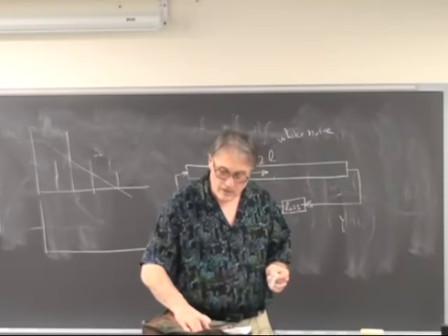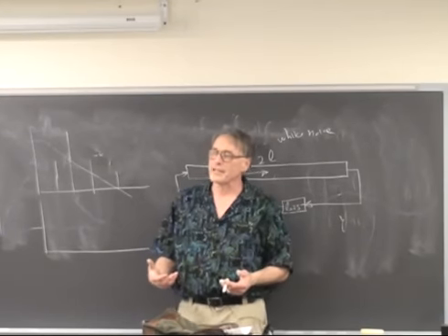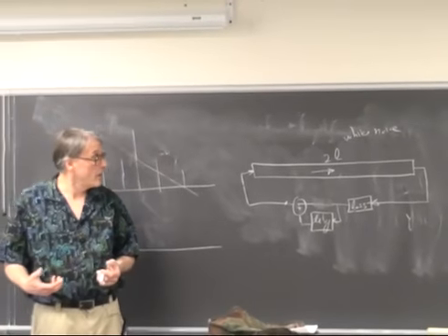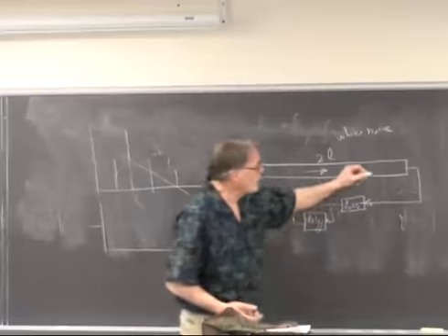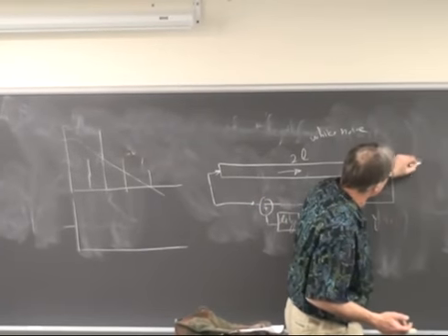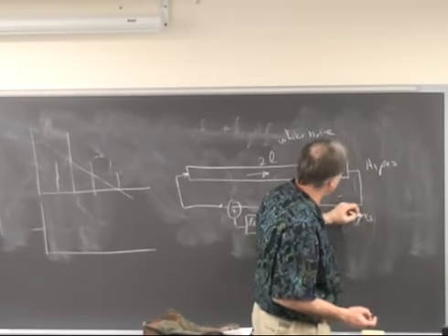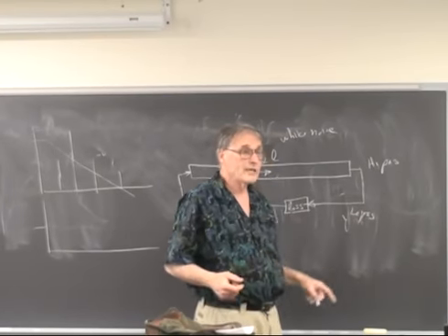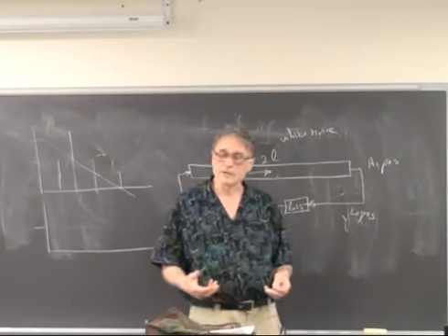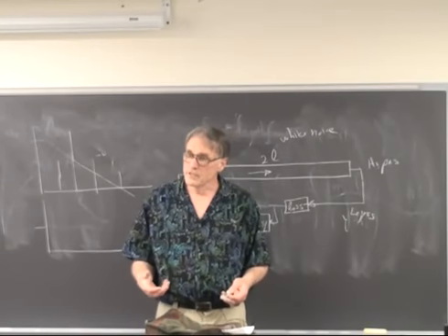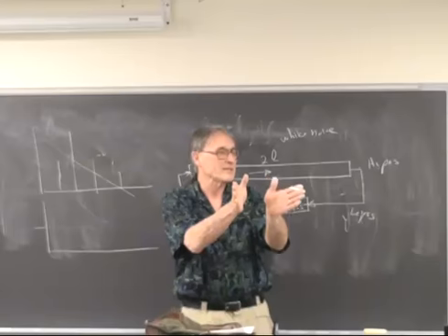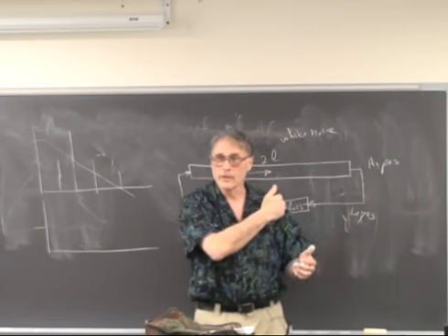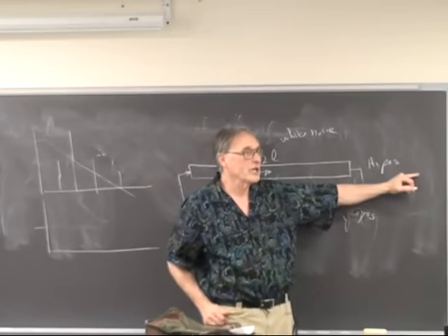So Karplus-Strong gives you a way specifically of making good string sounds, although people have added permutations of this. You put an output filter here, you put a high pass here, and a low pass here, and you make sure that the cutoff frequencies are the same for these high pass and low pass, and you make the cutoff in the hundreds of hertz, and it sounds like a horn. The reason for that is that the bell of a horn tends to pass high frequencies better than low frequencies. So the low frequencies get bounced back down the length of the horn and recirculate, and the high energy comes out the end of the horn.